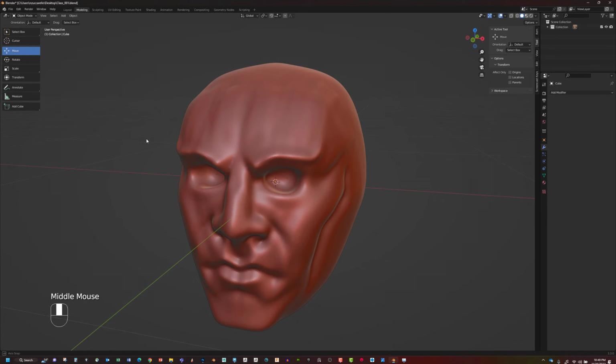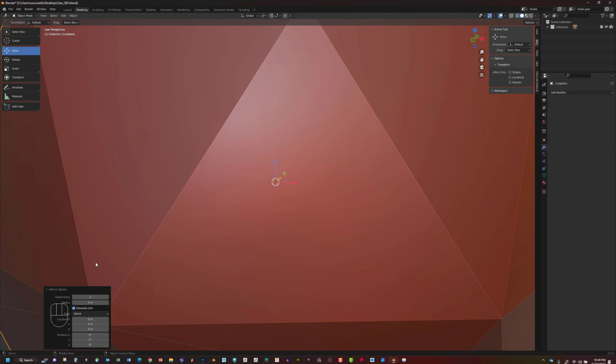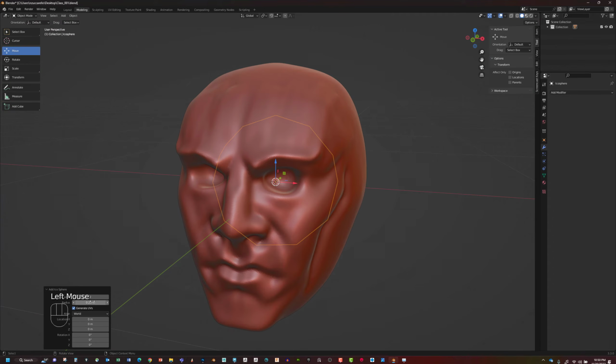So you might have that also in your quick favorites potentially for adding that. So if you go here, I'm just going to do the mesh. I am going to use the UV sphere. Actually, I'll do this isosphere. We'll do that, and then the radius of it I'll put at 0.25. Let's go lower than that. We'll go even like 0.1. And then what we've got for resolution on this thing, let's get this menu out of the way.